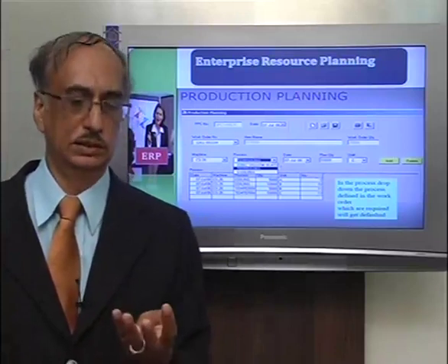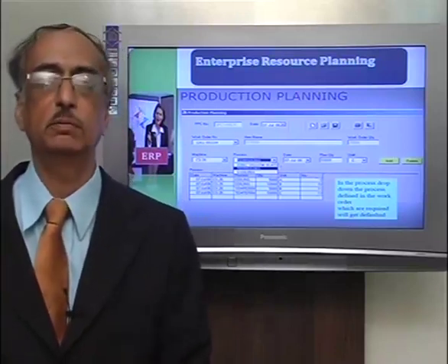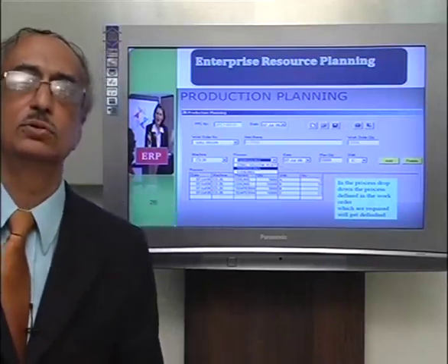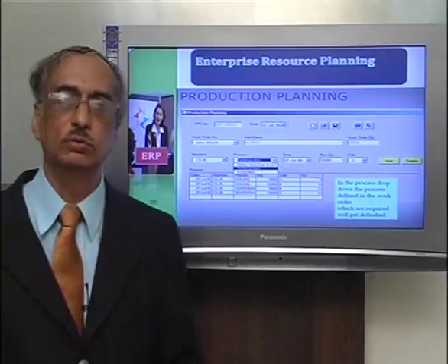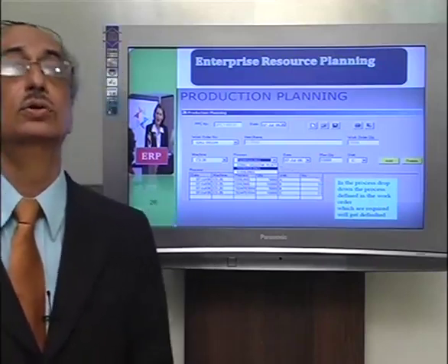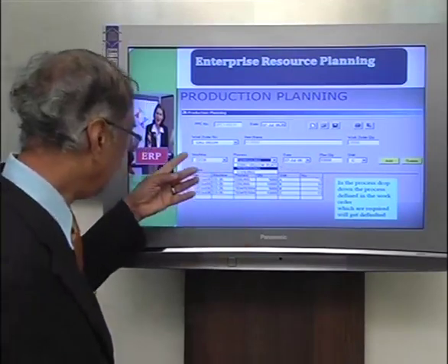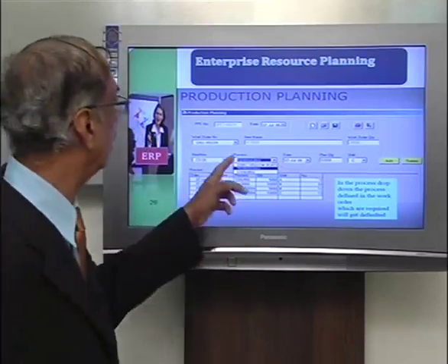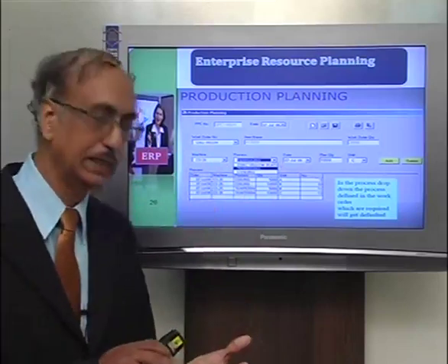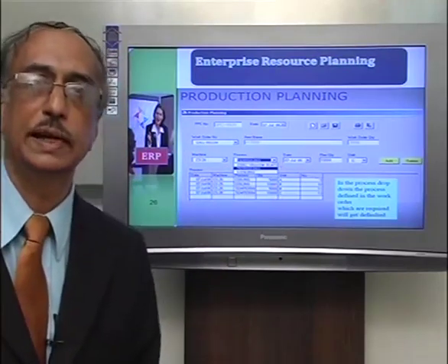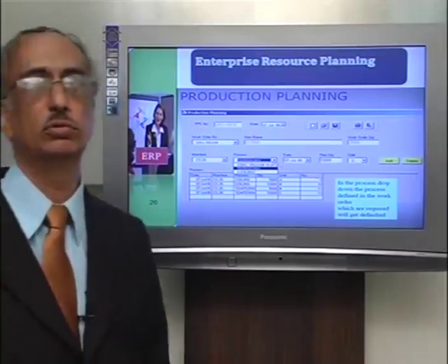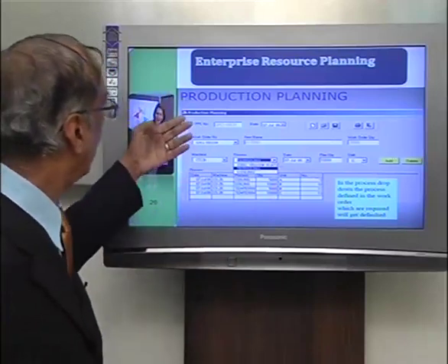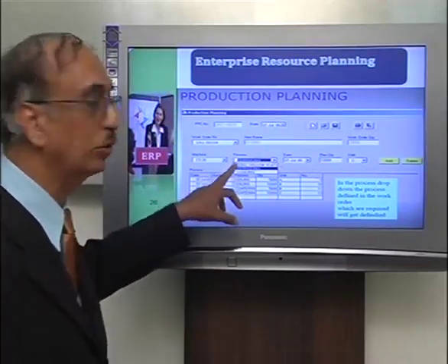The first thing is that you should have the drawing of that particular part. Second, you must have the bill of material of that particular part, so that you know what assemblies are involved in it. And third, you should have the process layout. Process layout is that the first process is say cutting, drilling, grinding; that sequence is mentioned in the process layout. So basically, the production planning consists of 3 things, out of which the processing part has been shown over here.